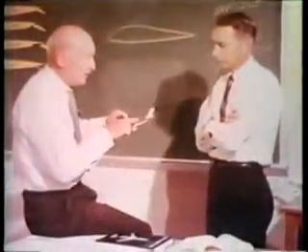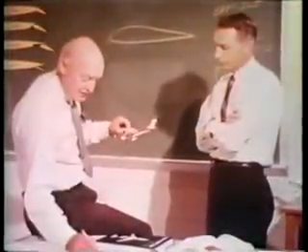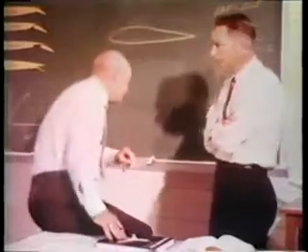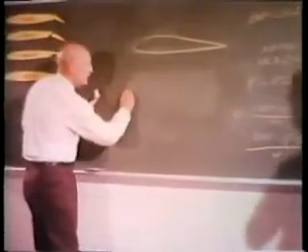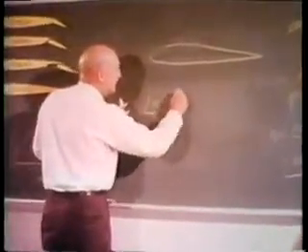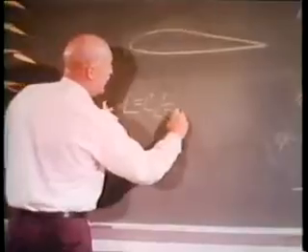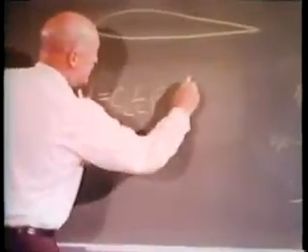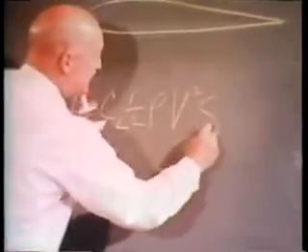But if you asked an aeronautical engineer to answer our question of how an airplane flies, he'd say quite properly that, very simply put, it's primarily because lift equals the coefficient of lift times 1/2 rho, the atmospheric density factor, times the velocity in feet per second squared times the total wing area in square feet.